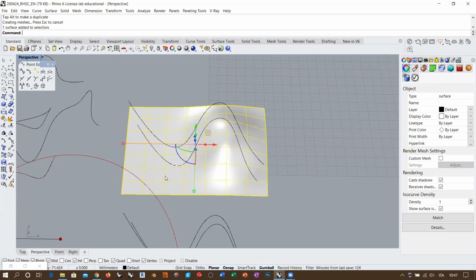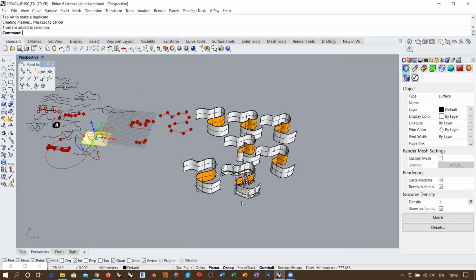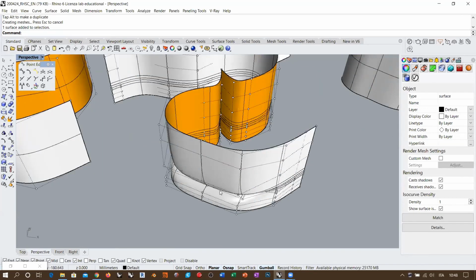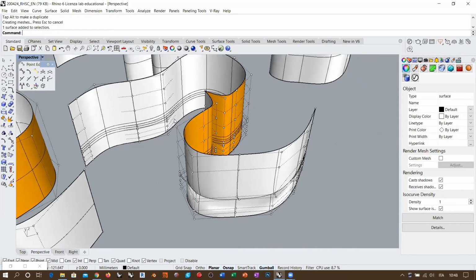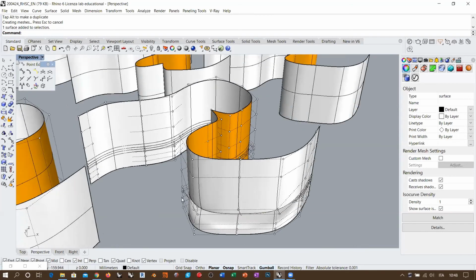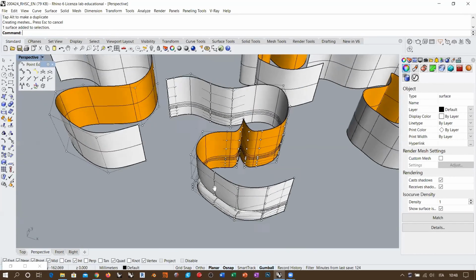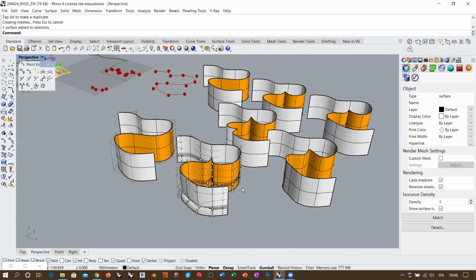So if I need, for example, more control points in this spot, I will have more control points along this direction and along this direction. So I am inserting lines of complexity, and these lines propagate all over and all along the surface. Having inserted control points, kink points, and so on in this area also affected the presence of more kinks and more control points along the surface at the same height. This is because Rhino works with the NURBS object.